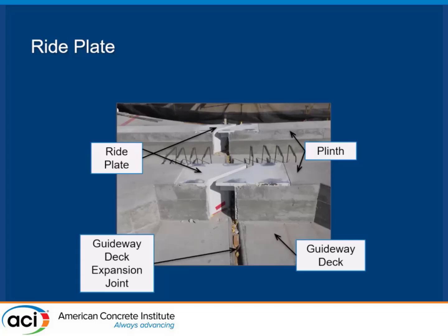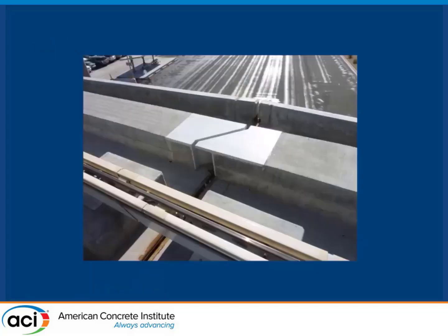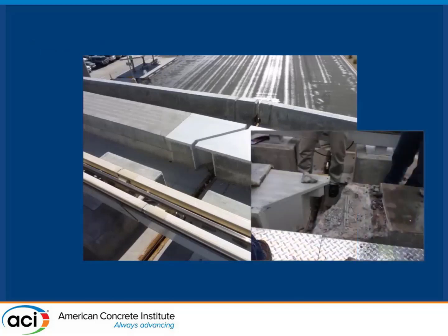In this case, they have a plate at an angle, and they put headed steel anchors in here and down here, and they just didn't go through checking all the different modes of failure that could occur. And so after less than 20 runs of a tram, it popped off, right? One of the embedded expansion plates popped off here.